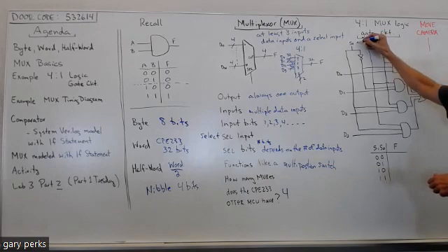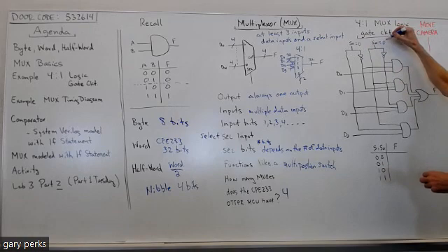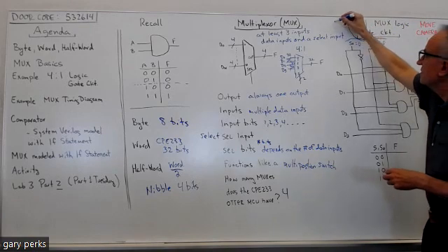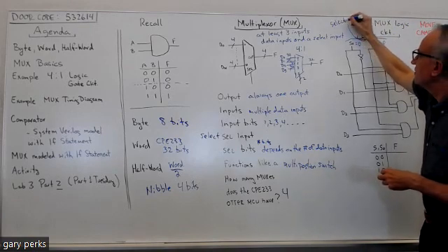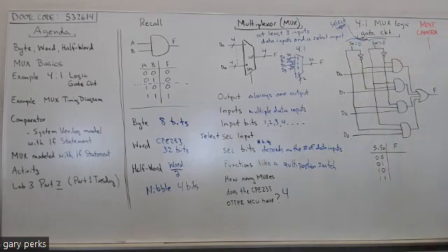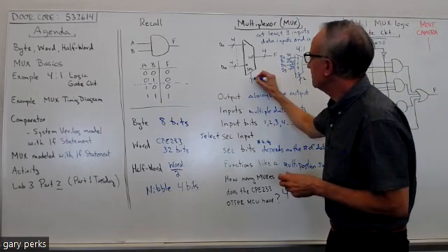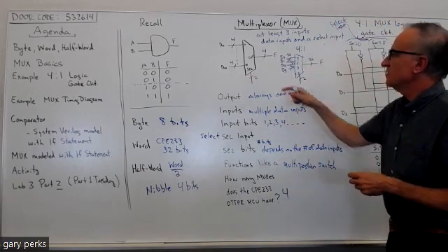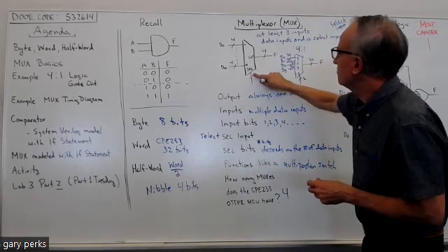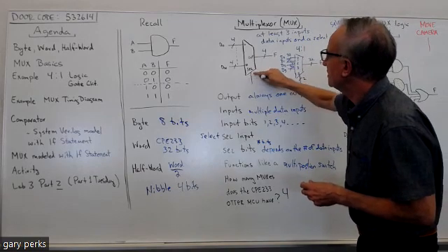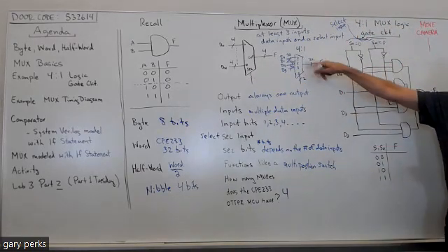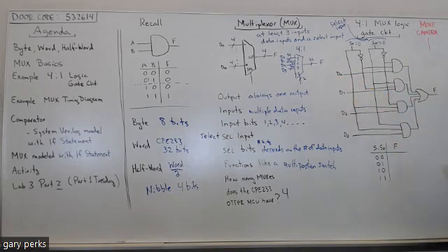So S0 is 0, and S1 is 0. You see these bits here, those are the select bits, our select input. I forgot to actually write the 2, but like we said earlier, this would be a 2. Well, no, I'm sorry, I wrote it over there. We didn't say how many inputs here. I wrote it here. So 4 inputs, so 2 select bits. Both bits are 0.